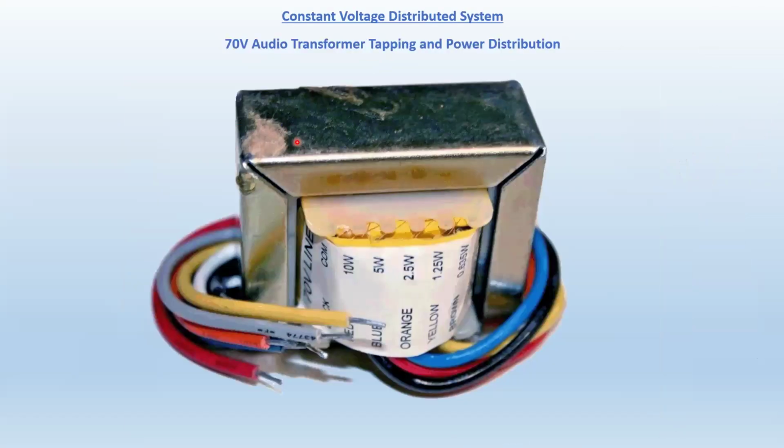We go. So we have many wires, and for example, here's something that's called a 70-volt line. There are, in the industry, 2 types of constant voltages being used: 70 volts or 25 volts, AC RMS. So if it's a 70-volt line, the amplifier has a 70-volt output, and that's where you connect the main line.